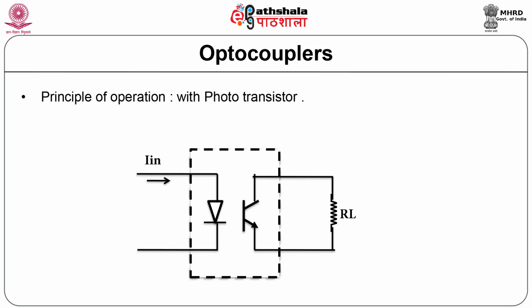Phototransistor. Since the CTR of an optocoupler with a photodiode output is so low, that is 10 to 15%, a preferred approach is to replace the diode chip with a silicon bipolar phototransistor. The bipolar transistor with its inherent current gain will provide a considerably higher CTR, that is between 50% and 100%, depending upon the beta of the phototransistor. The base lead of the transistor can be reverse biased to reduce sensitivity, forward biased to increase sensitivity, or left floating or disconnected.